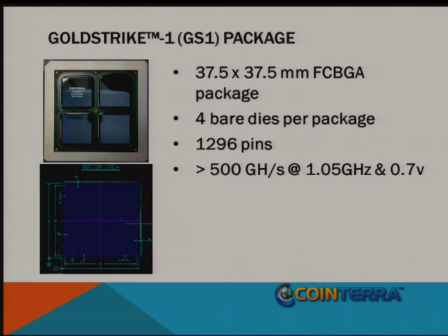So we package this die into a 37.5 millimeter by 37.5 millimeter full flip chip BGA package with 4 bare dies.